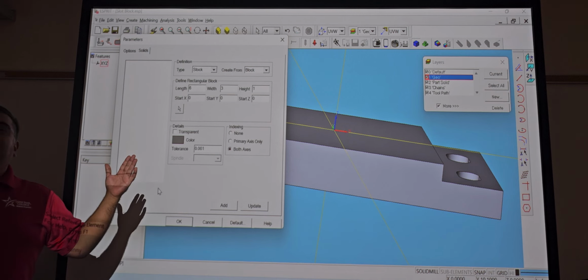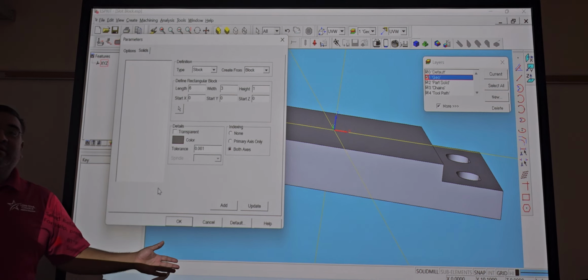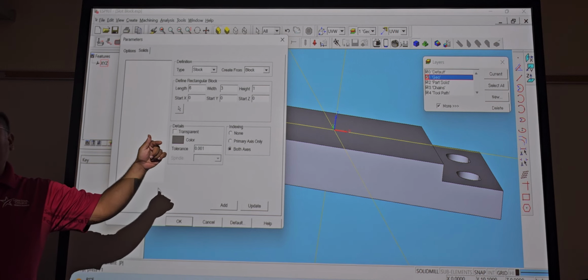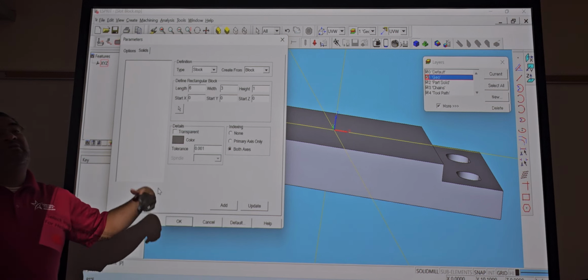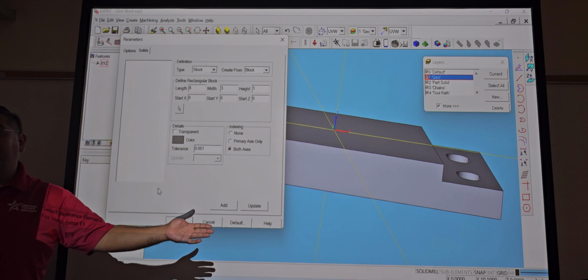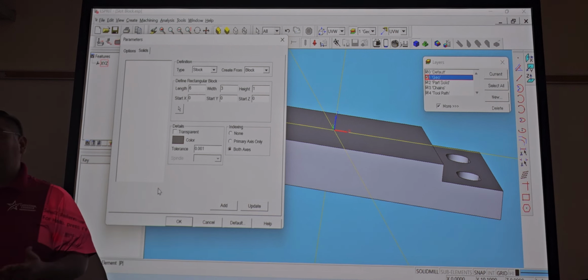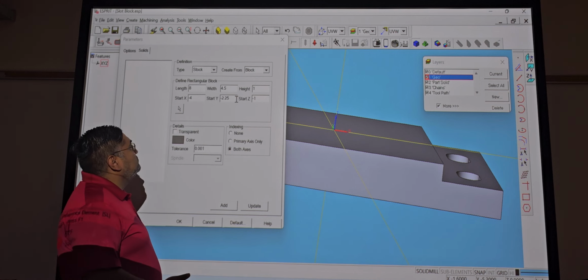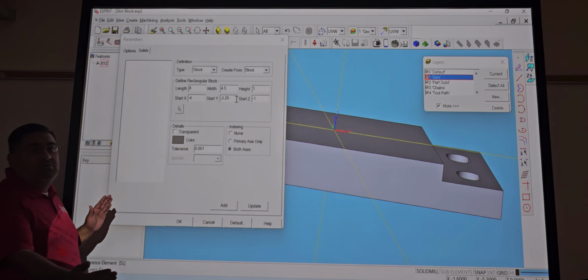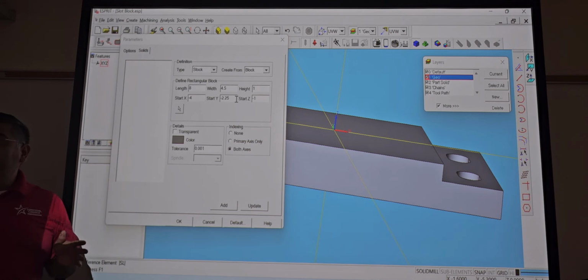So it's not all the time, well, it didn't crash here. Yeah, bro, but you had 150,000 more material on this side, and you try to take all that off in one shot, where it could have handled what you were gonna take off here, but since you have another 150 or 200,000 in real life, that's why we crashed, right? So you always wanna double check that. But the easy way for this one, push the arrow, click on your part, see how it adjusted my numbers for me, right? So let's say that my part actually came a little bit wider than what I had. Instead of it being 8 inches, it actually got here at 8.5, correct?